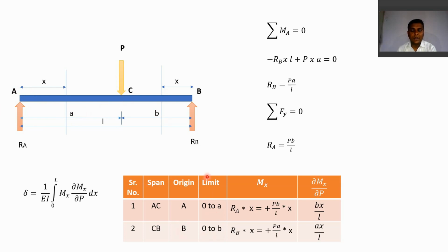Now after this we will discuss how to get the equation of a bending moment. Let us again consider the first part, that is part AC. When we are taking a section over this part AC, we can consider its left hand side to get the equation of a bending moment. On the left hand side of this cross section we have reaction RA.